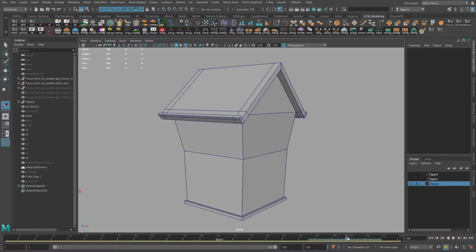Let's add some divisions to the bottom part of the house. Okay, so let's add 4 vertical lines to one wall side, 5 vertical lines to another wall side. Do not forget to add 2 horizontal lines and shape the lines for a doorway. Then select the faces and do extrusion.